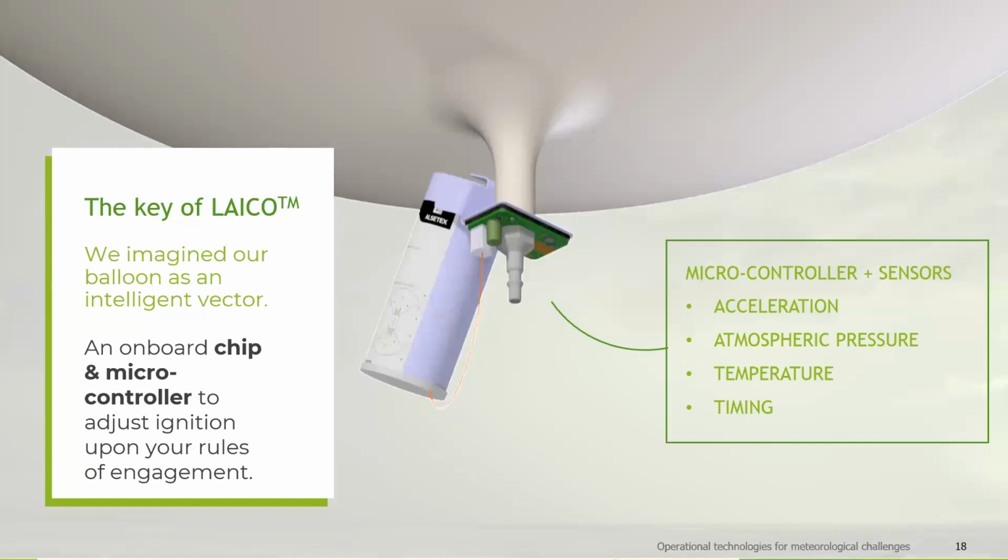So basically, this is just a slide that shows the setup they have with the balloons. Here you have the flare. The flare can be ignited by a microcontroller on this electronics board here. The electronics board in their system measures the acceleration of the balloon as it's going up, and measures atmospheric pressure and temperature, so that you can time the ignition of the flare, and the injection for that matter, exactly when you're in the best possible condition for doing the seeding. So this is basically the approach that we're looking at.